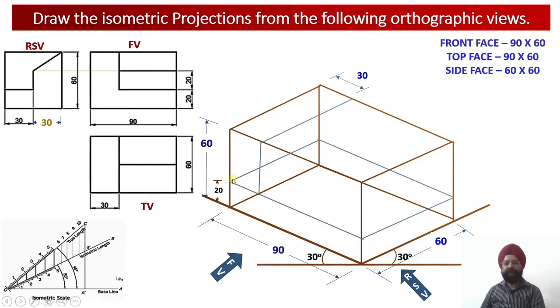Whereas for the remaining 30 millimeter, this is my remaining 30 millimeter. For the remaining 30 millimeter, I am going to have the top face, which will be a straight parallel surface, and from the front side, this parallel surface will be moving down as a flat line, so that this L construction I will be obtaining. Okay, so now this is the horizontal segment corresponding to this 30 millimeter width over here. This is the horizontal segment of the top, and this is the vertical segment which is starting from the top and it is moving 40 millimeter down, so that it is going to coincide with this ring which I have created, which is at a height of 20 millimeter.